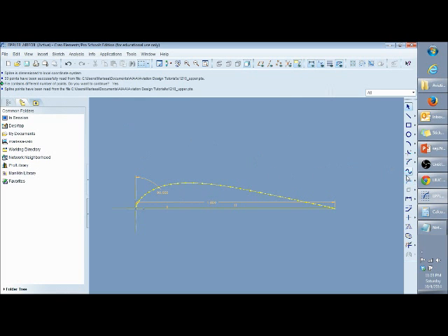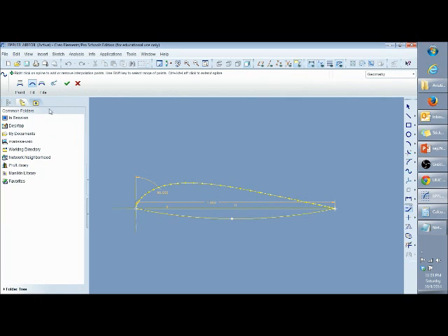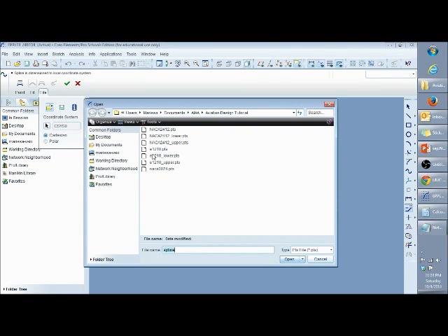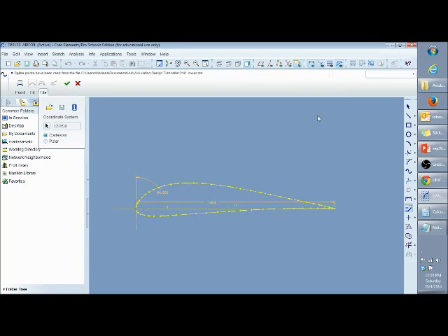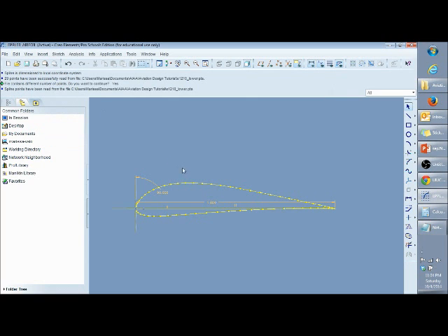So what we're going to do now is the same steps for the bottom, the lower half of your curve. And same as the top one, keep in mind where your airfoil's origin is and where it ends. And a very important step, because it will freak out when actually creating the extrude for the part: the 1 inch line that we originally put in, you'll want to delete that.